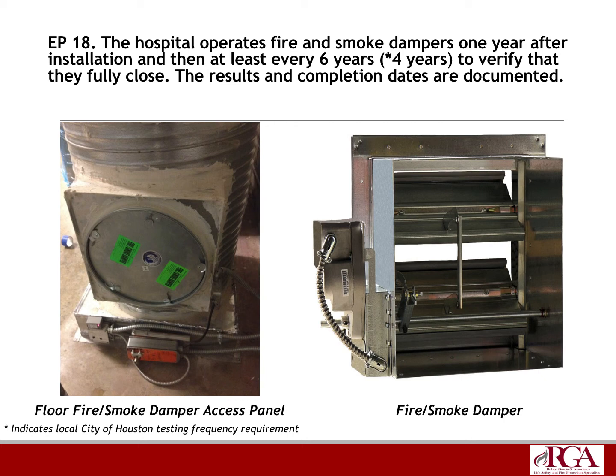I know it's a rigorous test as far as getting access to these dampers when they're in certain spaces. You may even have to enter patient rooms, or you have to have mobile containment because you're in certain critical areas. But if you recall, when these tests occur, almost always you have multiple mechanical failures. If you're testing these and consistently having failures, to me that tells me either the frequency has to be increased, or they just have to be maintained better, because a fire damper in essence is basically a fire door within the ductwork.